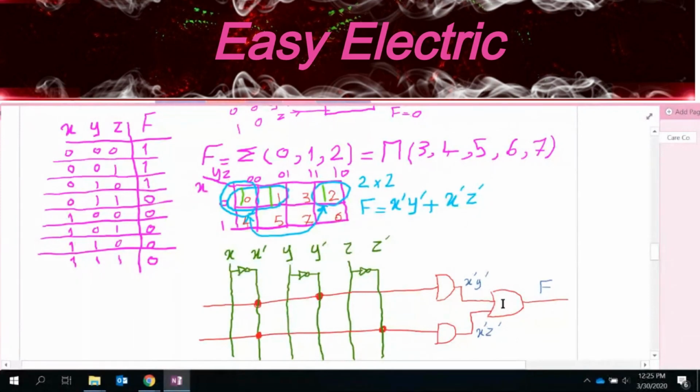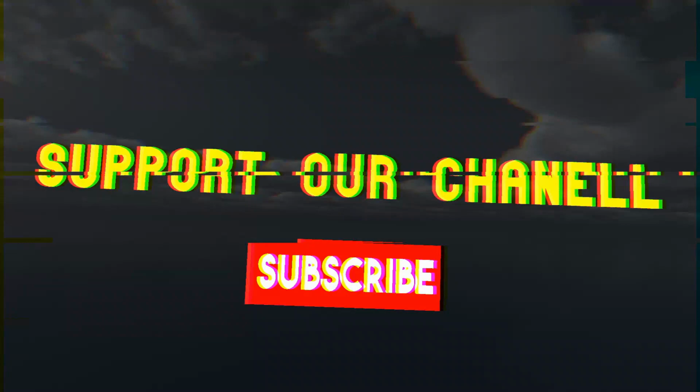Definitely for that form here, you should get one AND, because you end up with the product of sums, right? I just guess. So here should be changed to the AND, and these two should be changed to the OR, because it ends up with the product of sums. For a sum, you need OR. Probably you will have two OR here, and you need one AND here. Okay, that's my guess, but you could do that. Definitely you end up with the same.